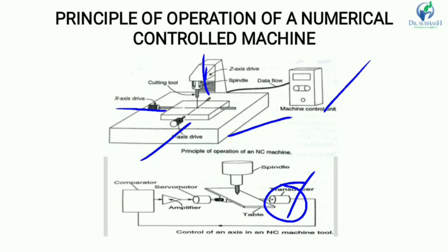The input is then given to the Z-axis servo motor to perform the operation. The system switches on the motor driving the spindle carrying the drill and commands the Z-axis servo motor to move at the program feed rate into the workpiece till the program depth is reached.